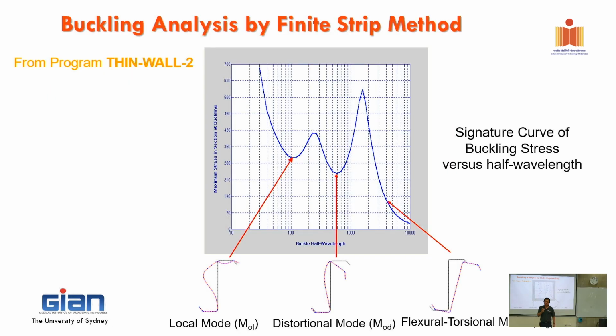Remember in the effective width, that equation already has a little bit of interaction in it. This is pure local buckling. So maybe it's slightly different because in the effective width method, you go straight into the strength equation. But this one is local buckling. But in the DSM equation, there's the interaction in that, so it comes in. So this is the pure one.